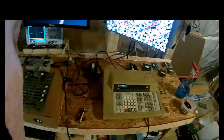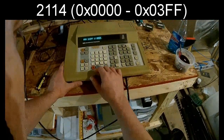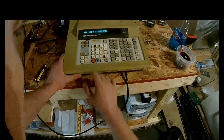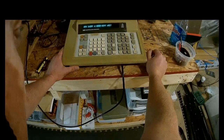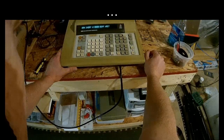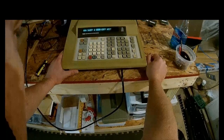We know that 2114s are in 0000 to 03FF. So let's do a RAM short on those. It should come back any minute. The RAM short's pretty quick, and it's okay, so that's good.